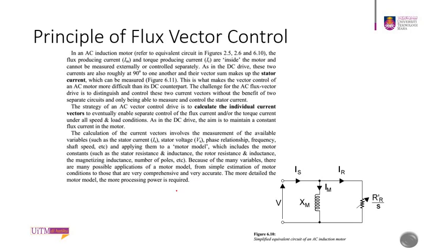Of course, all this requires more processing power, so you will need microcontrollers or microprocessors in order to execute this. Compared to a normal DC motor, where it's straightforward, you can control your rotor by limiting the voltage using resistors and so on, manually. But for this, it will be more complicated, and it will use more processing and calculation power. Okay. But it's not a problem now because of the advancement in microprocessors and microcontrollers, and production-wise and cost-wise they are very cheap, so it will not be a problem now.